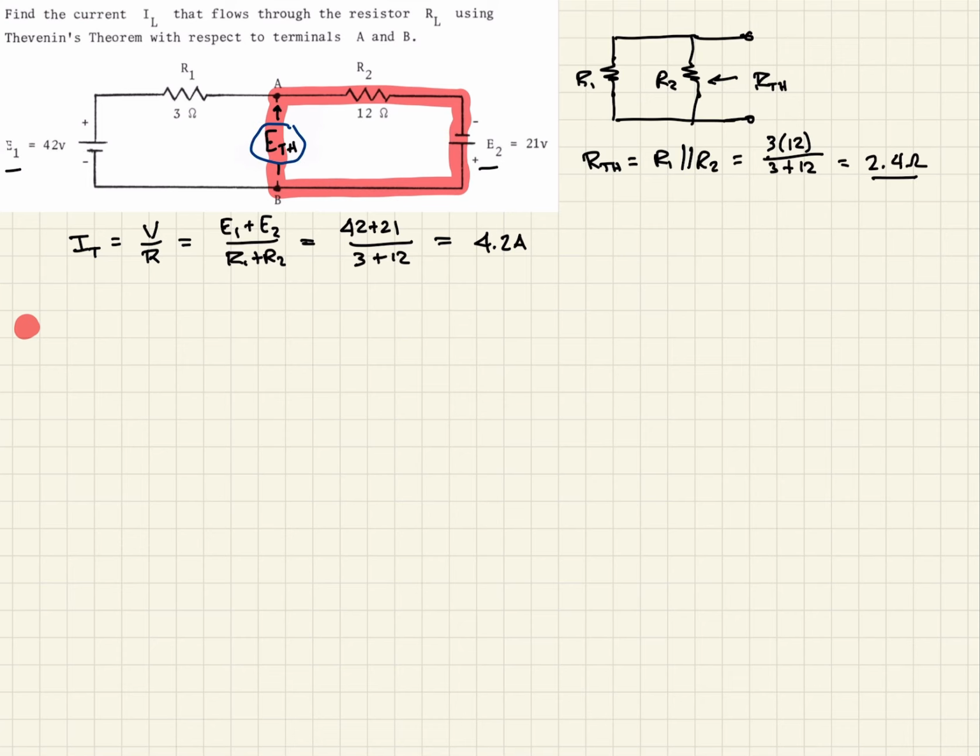And so we'll say our Thevenin, which will eventually be our voltage open circuit, however you want to call it. Same thing. That's got to equal the voltage drop across the rest of the circuit. So when we look at the rest of the circuit, the first one we have, we'll put in green here, is this R2.